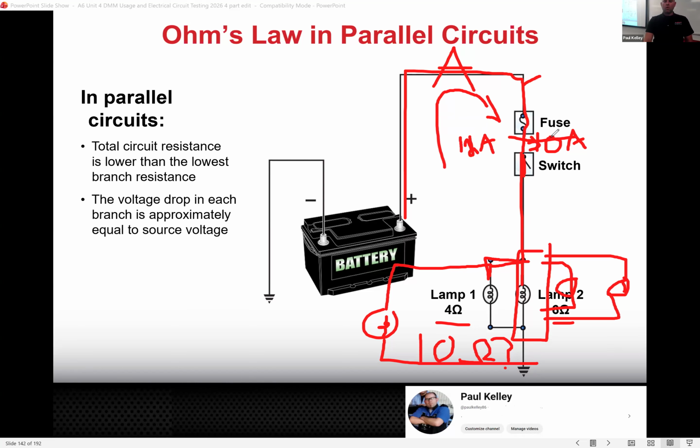If we start to flow more than 10 amps, like let's say we flow 11 amps, is there an 11 amp fuse? I've never seen an 11 amp fuse. So what do we do? We throw in a 15. We pull the red out and we throw in a blue, a 15. If you throw in a 15 amp fuse, which is weaker, the wire that can handle 12 or the fuse that can handle 15? Ooh. So now you start to overheat the wire. That's when it catches on fire.